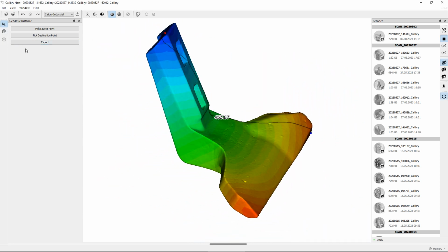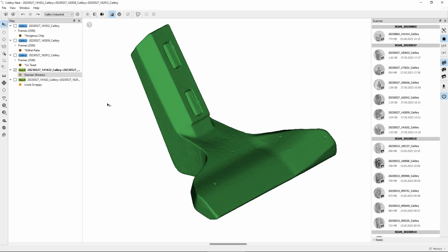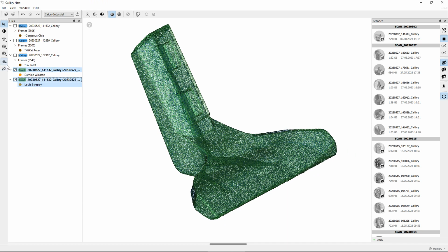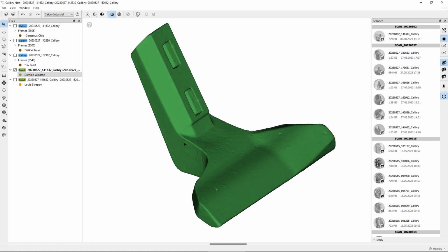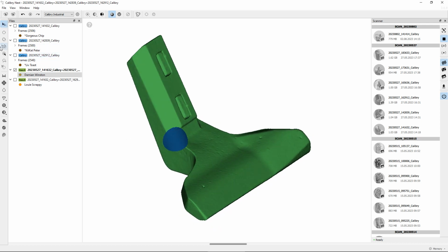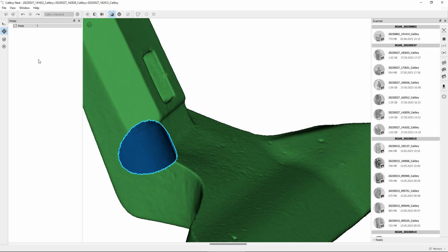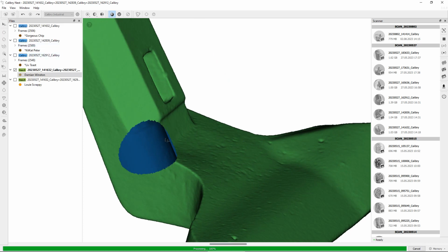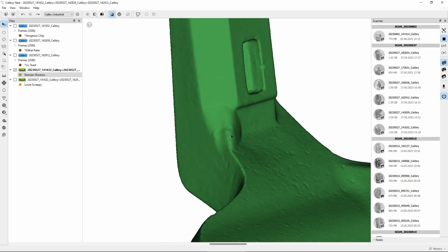All right. Another thing that might be useful for comparing two results is the so-called distance map. So we have the first part and the second part. In this case, they are pretty much similar. So let's maim this part a little bit. Let's say I'm going to cut this area from here and just fill the hole without any bridges or anything. Of course this hole wouldn't look as pretty as the original surface. So I just hole fill it like this, and you can see it's not how it was before.